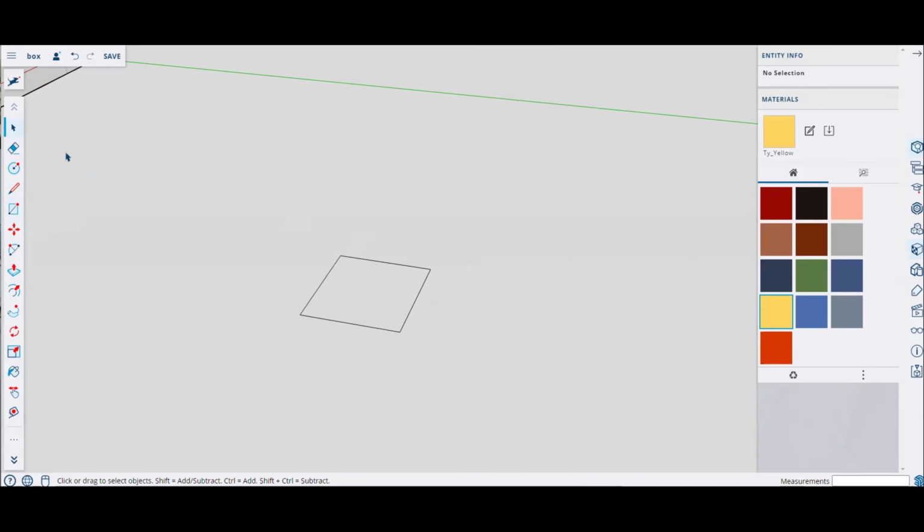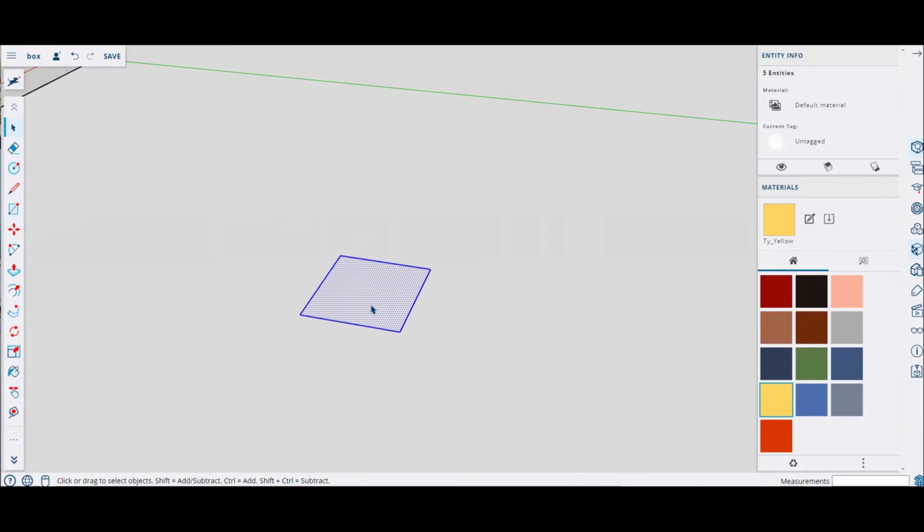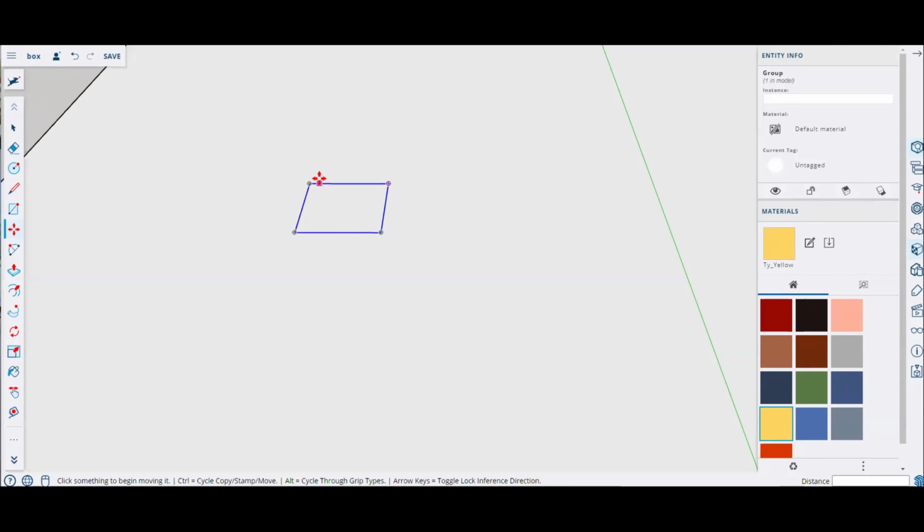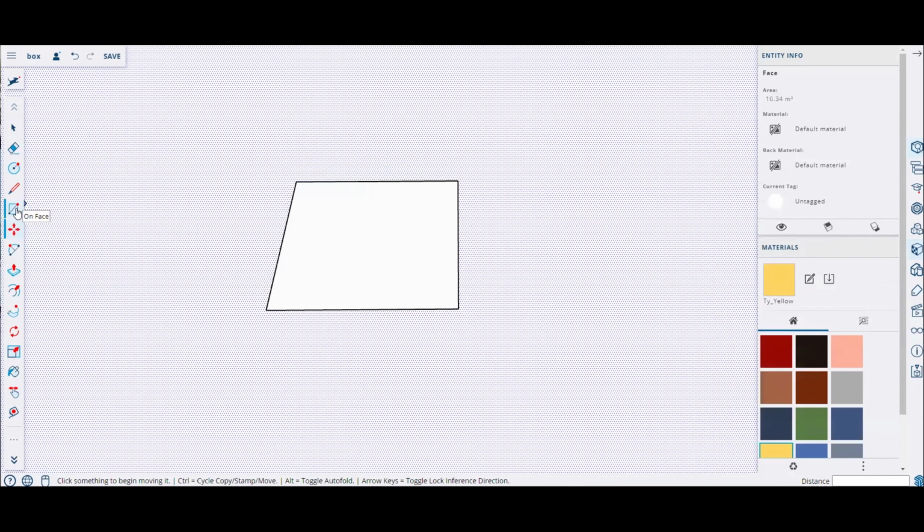All right. And then I'll press the select tool and select that object, right click. And you see a few little commands in here. We want to make a group, turn that into a group so that it doesn't become part of the same component as this, so I can move it as one without affecting it. So here's my print bed. We want to design an enclosure. Now I've gone through roughly what all these tools do, so let's use a few of them now.